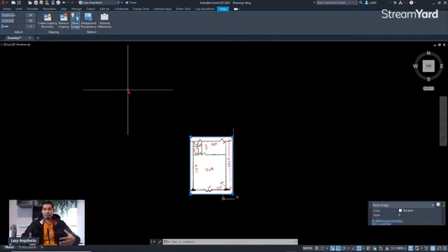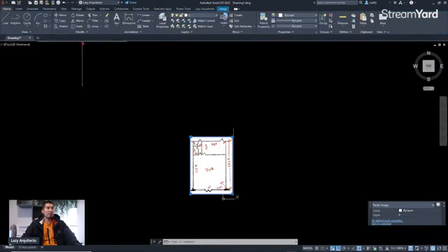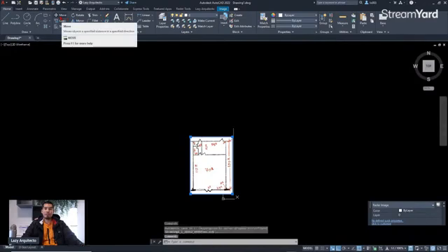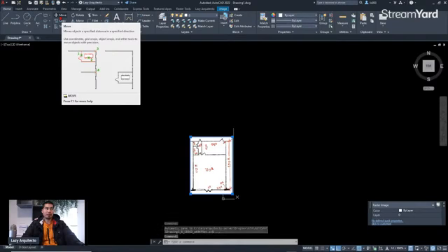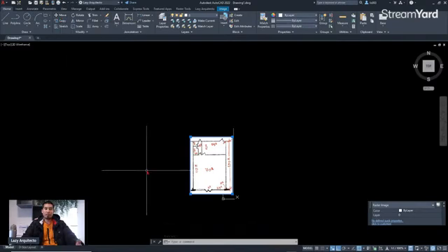You're not drawing something new, you are modifying this image. So of course, it's gotta be in the Home and Modify panel. So let me find the move command over here, and it's right here, Move. All right. Again, let me introduce its shortcut for the move command, and this would be M.